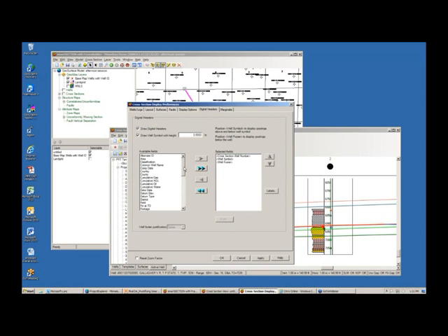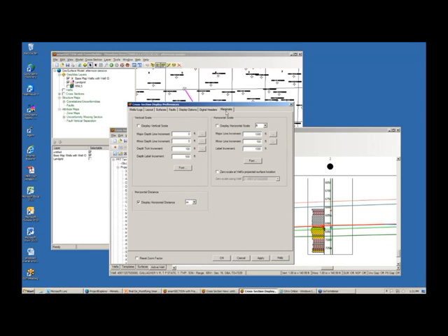The Digital Header tab is identical to X section, so it's something you're very familiar with. You can come in here and select different items that you wish to post at the top underneath your symbol. Marginalia is most probably frequently used by the horizontal drilling folks because they want to have a really good concept of the scale of their cross-section. You can put a nice graphic scale behind your wells and a vertical and a horizontal scale down to 2 feet if you wish, so you can keep that borehole tracking exactly where you want it.